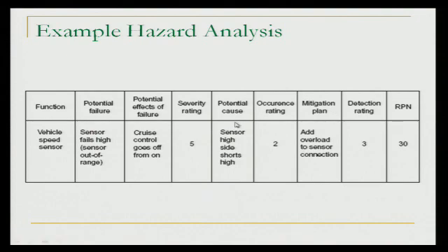What could be the potential cause of this failure? A high side short. The occurrence, how likely is it to occur? Low occurrence, relatively. What's your mitigation plan? Add overload to the sensor connection. In this particular case, you would add a more robust sensor connection.